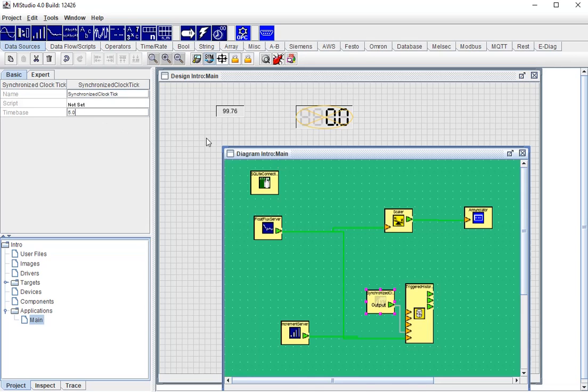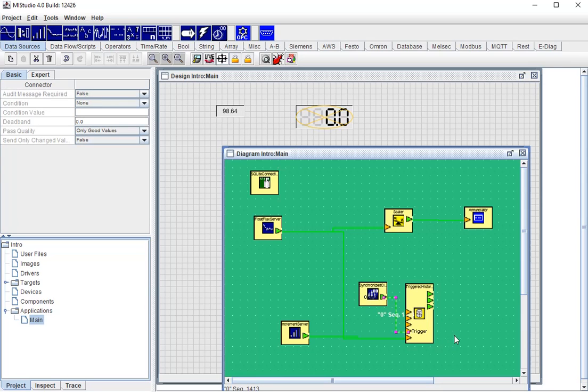To avoid problems with live data, MIStudio starts out in simulation mode and won't save data to a database, won't communicate with the PLC until we go from simulated to live mode. As soon as we do that, we'll see that we're saving data. So now we're populating our database with a table that has a column for the current time and the values of these two components.